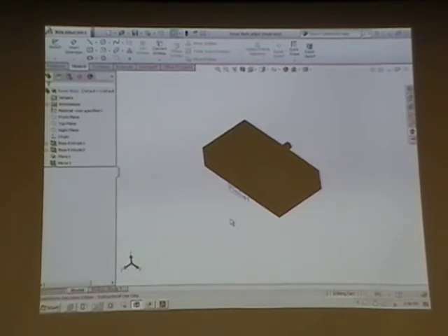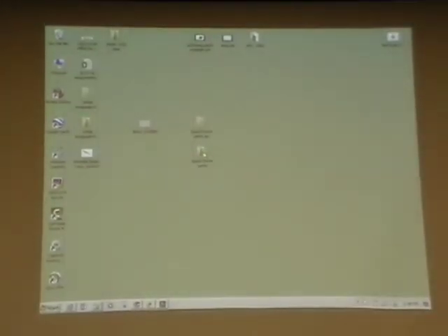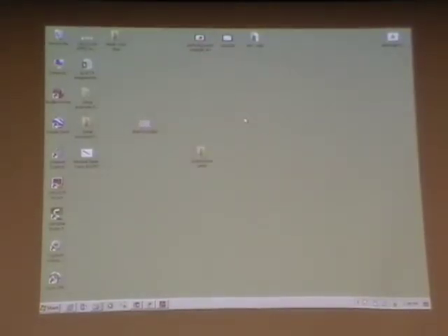Compressing the file is a little bit like encrypting it, because you're actually changing the bits of data, and that causes all kinds of problems for SOLIDWORKS. So the important point to make here is don't work with the zipped versions of the files. In fact, after you extract the files, I would encourage you just go ahead and take that zip file and delete it. Get rid of it, that way you don't accidentally pull a part out of it and mess up your whole assembly.